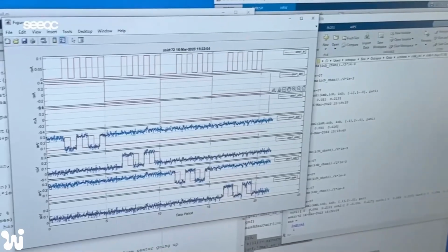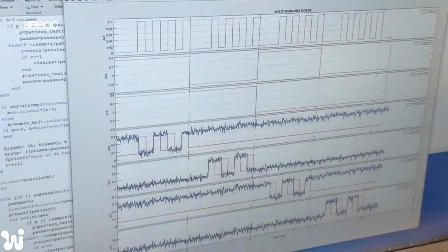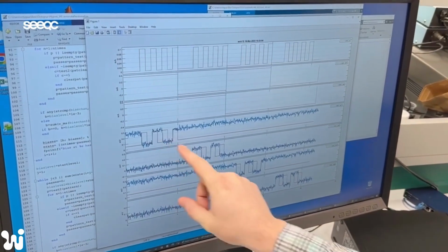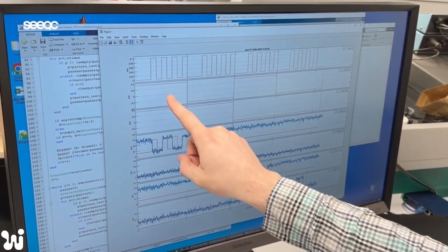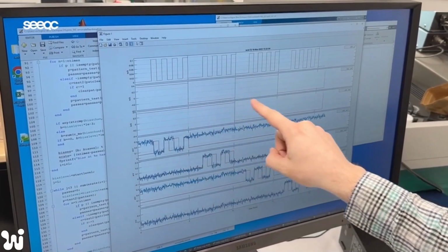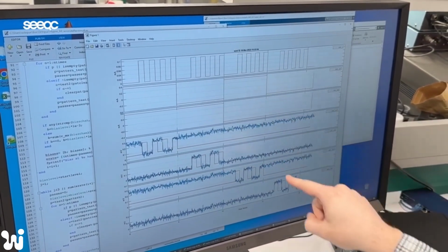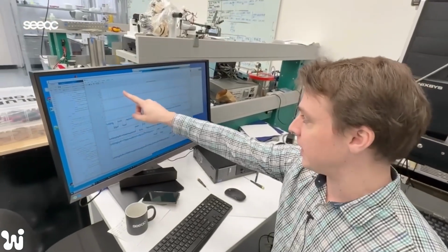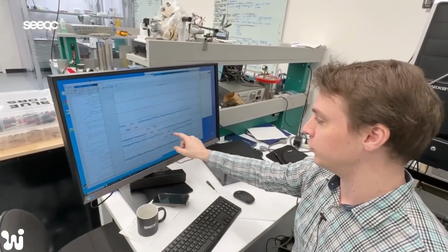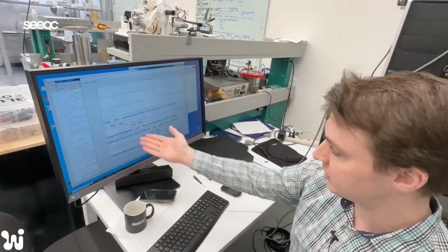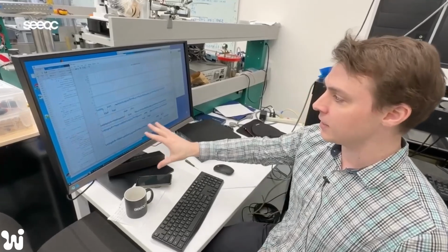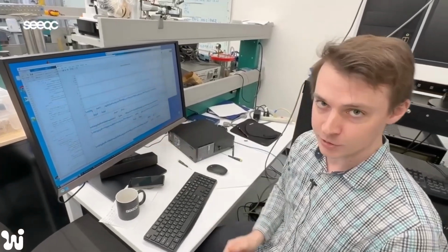So this is our 4-output switch control demultiplexer, in which I am addressing each of these 4 outputs by turning my 2 switches to a state of either 00, 10, 01, or 11 to address each of the outputs in series. When I address each output in turn, I expect my input clock to pass through to the appropriate output, which is what I see here, with each output in turn triggering, and none of the other outputs triggering when they're not supposed to.